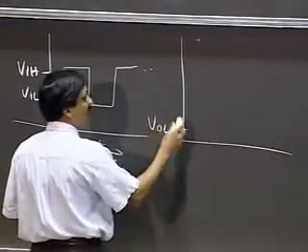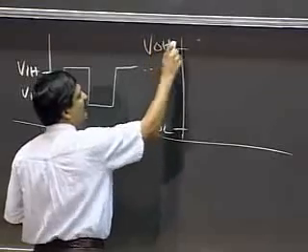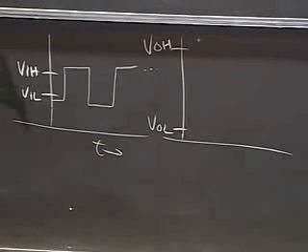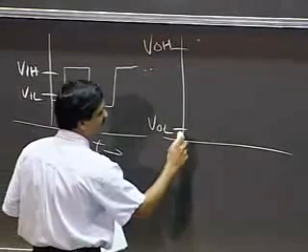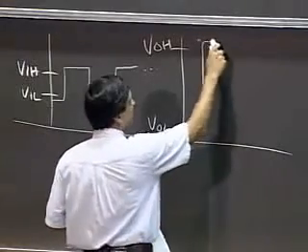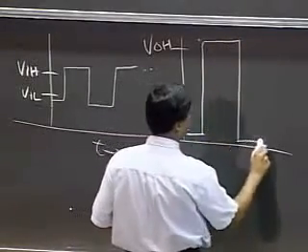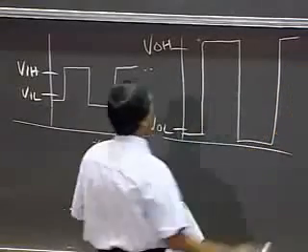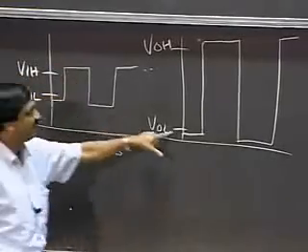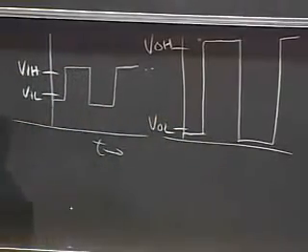I would have VOL, VOH. So at the output, I'm required to stretch the 1s and 0s to be further apart from each other so that I get some noise margin. And the corresponding signal for our little circuit would look like so. If this is a valid input, then this would be the corresponding valid output.